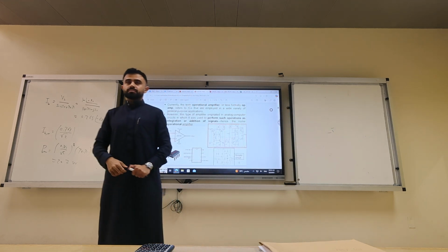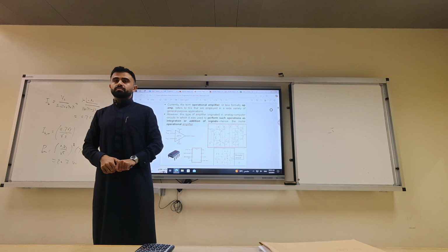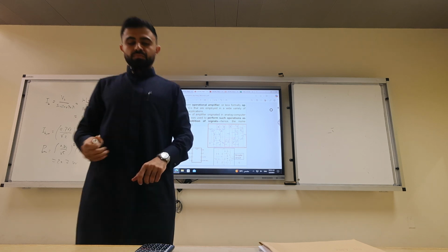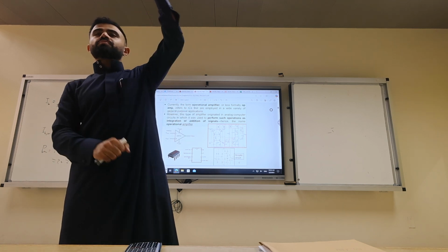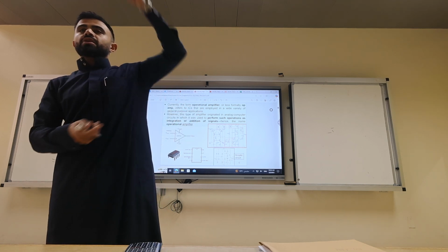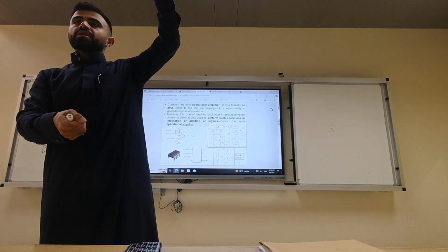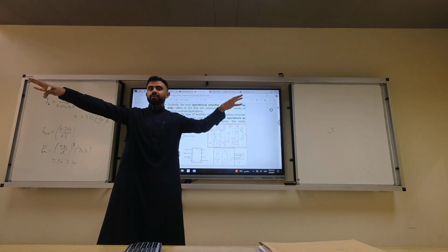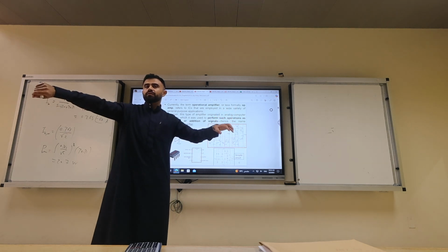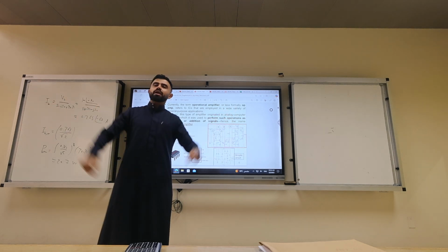Transistors. Using the amplifier, shouldn't the maximum voltage be 3? No, for this it's not plus V supply, minus V supply. Here the whole thing is 1.5. In the plus V supply, minus V supply case, you have 5 volts, but you connect to the negative of it. That's how you get 10 volts.